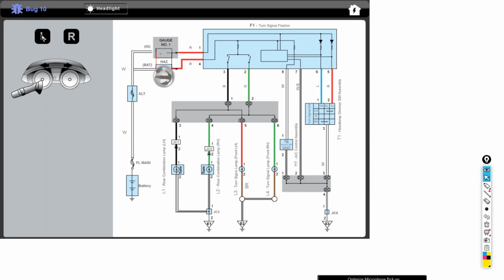Where you have a parallel circuit with multiple bulbs, this works very well for testing like that. Because sometimes when you unplug one circuit, if half the circuit's still plugged in and the other half is unplugged, all of a sudden the bulbs come on dim, then you know you just created a series parallel circuit.